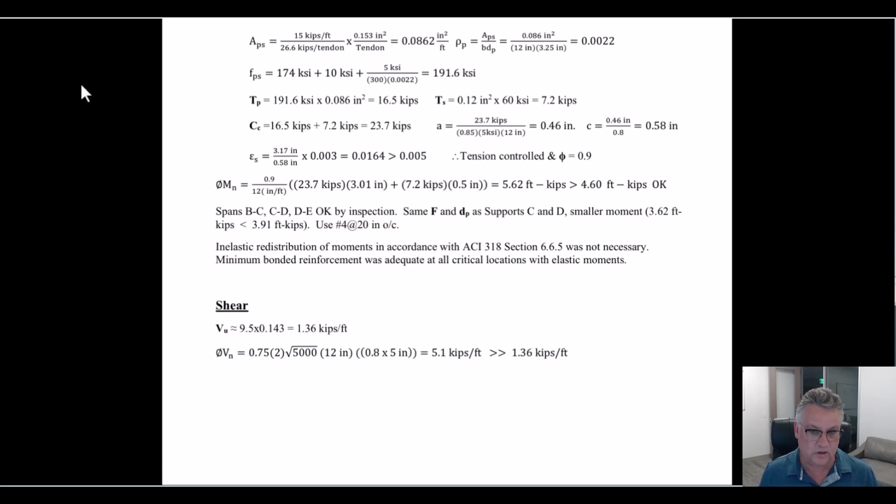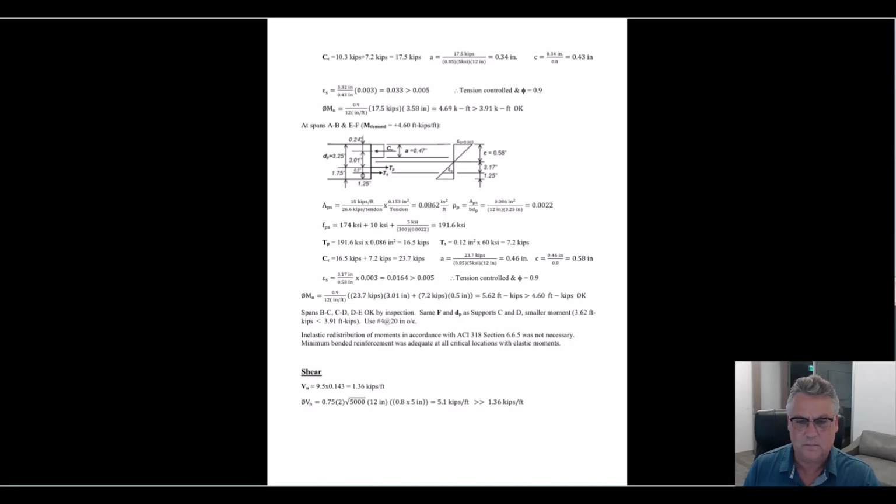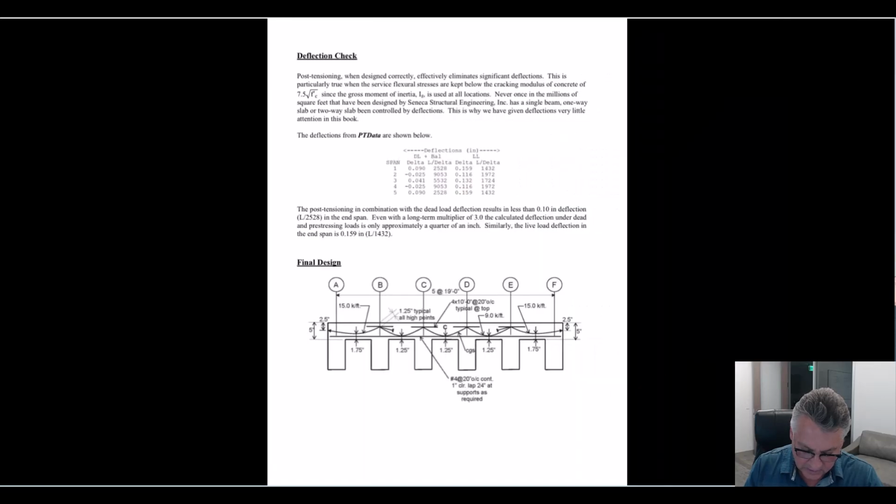It's not like two-way slabs that you're going to see, which bring all of their load to a localized point at a column. That can be difficult to resist when you're lumping up all of your shear demand at one localized point. You likely have a shear problem that you have to think about and design for. When you're continuously supported, which is what one-way slabs are, it's very difficult to develop a shear problem. So that was the example that my dad came up with.